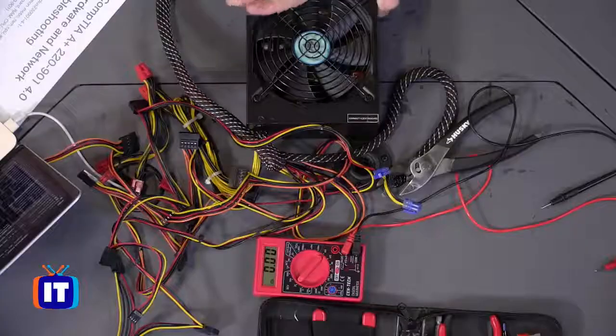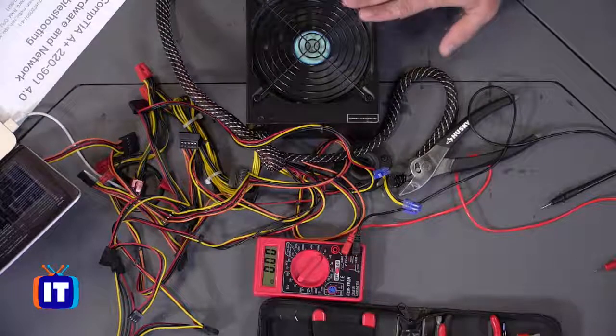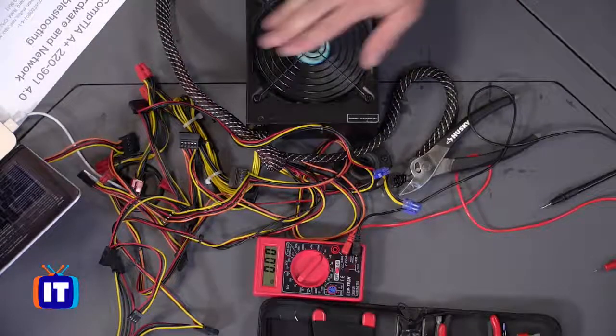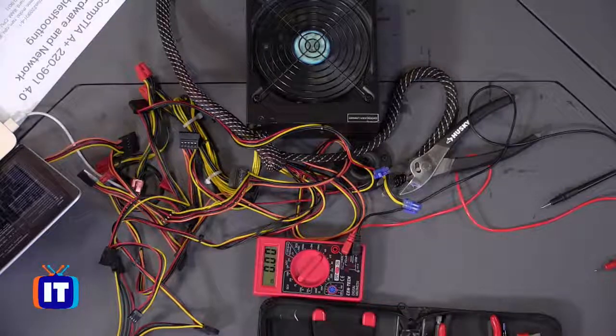Now, that being said, there are some basic tests that you can run on your power supplies if you feel like maybe the fans are spinning like we've shown you and we're not getting power to the machine. You can pull out your multimeter. We've got a power supply already set up. Here's our power supply, about a 1100 watt power supply, and we'll turn it on here and let it start up. Again, if something like this happened where the fan is spinning and you have no power, that's a good telltale sign that something has failed on the power supply.